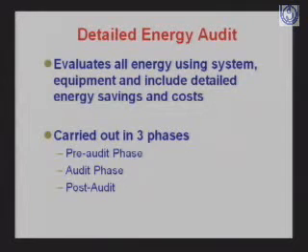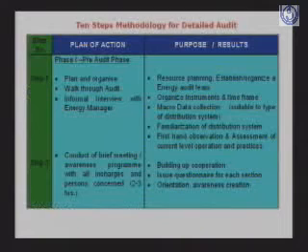The detailed audit evaluates all energy using systems and equipment, and includes detailed energy saving and cost. It's a complete audit. It covers 100% of energy use in a particular facility or system. This is carried out in 3 phases: pre-audit phase, audit phase, and post-audit phase.